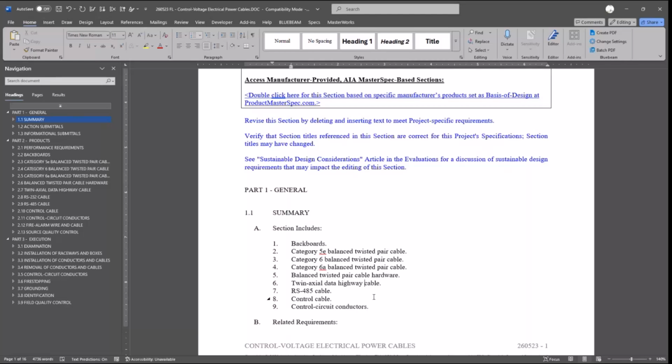And usually whenever I kick it back like that, I'll have them go through and mark every single sheet with what division it is, is this 2.10, is this 2.11, strike through what you're not using, highlight what you are using. I kind of crack down on them like that, and they hate it because it's very time consuming for them. But contractors that normally submit 800 pages of that are usually trying to cut corners, and that's usually where very expensive mishaps happen later on.